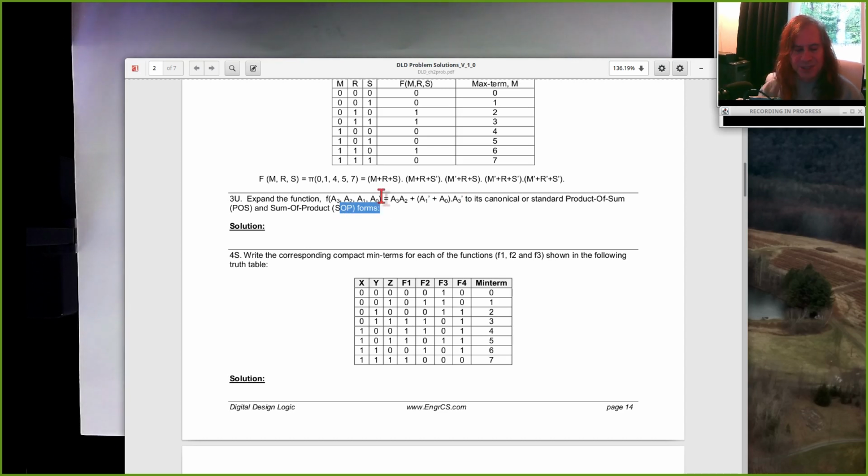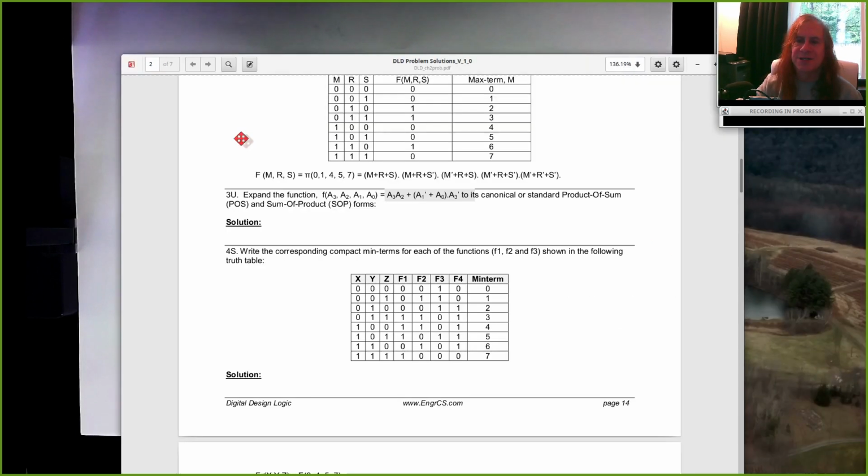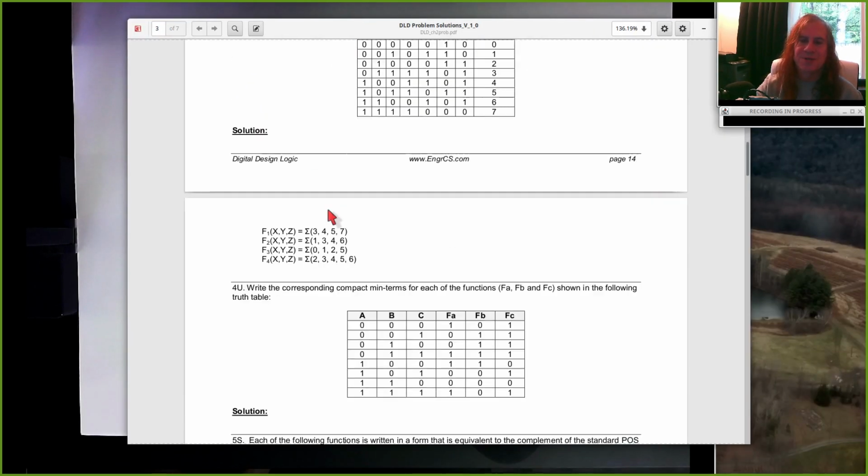But as you're doing this, think about what it is you're doing, and you'll probably start to understand this at a deeper level. And eventually we'll see shortcuts for going, say, directly from this to a sum of products. But for starting off, work very methodically. Take this, write a truth table for it, and then go through and use this kind of idea to write a sum of products. We'll talk about product of sums on Monday.